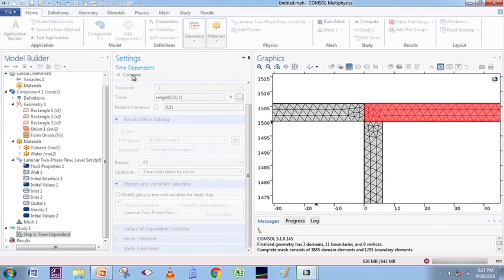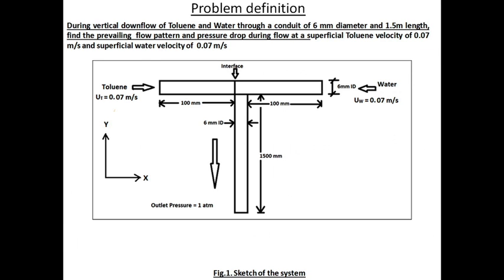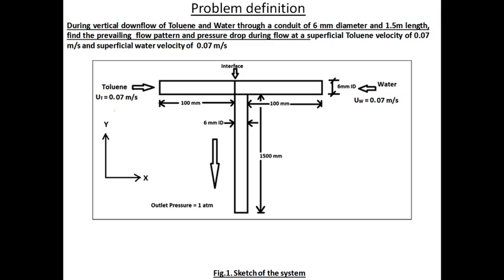In this situation, as I earlier said, it uses 2 different types of solver, that is direct and iterative method of solution. For 3D or complicated geometry, it is best to go for an iterative method of solution rather than the direct method, since with the direct method your system might hang or slow down, the progress will take some time, and it requires a huge RAM for computing. GMRES is the best iterative method for complicated geometries.